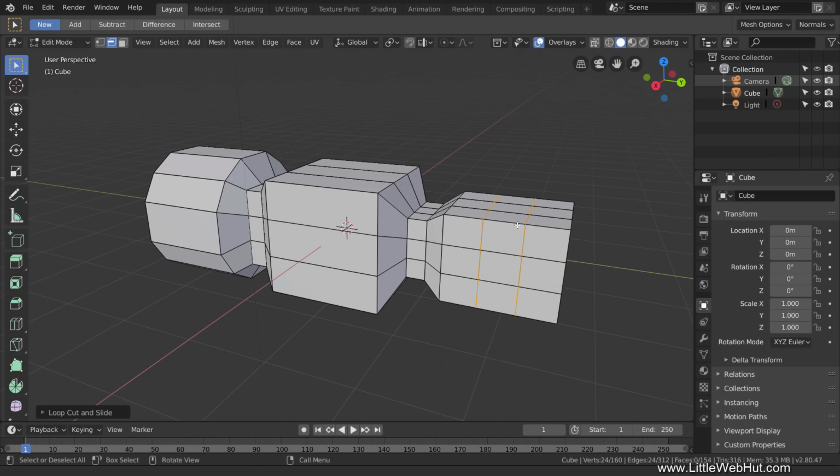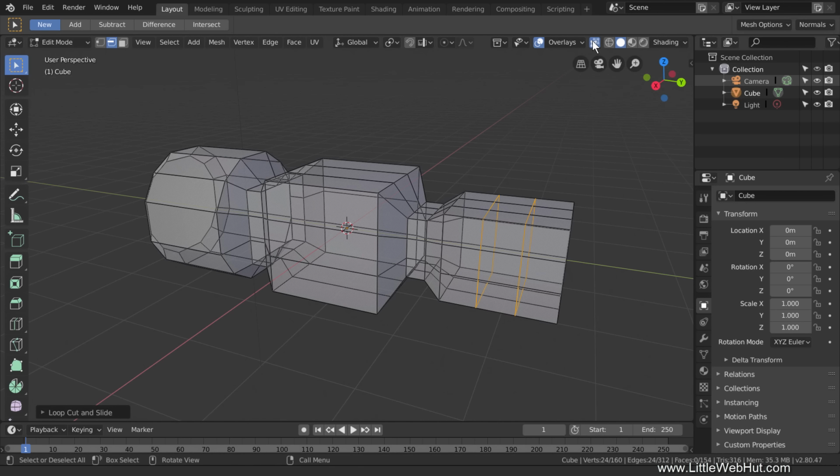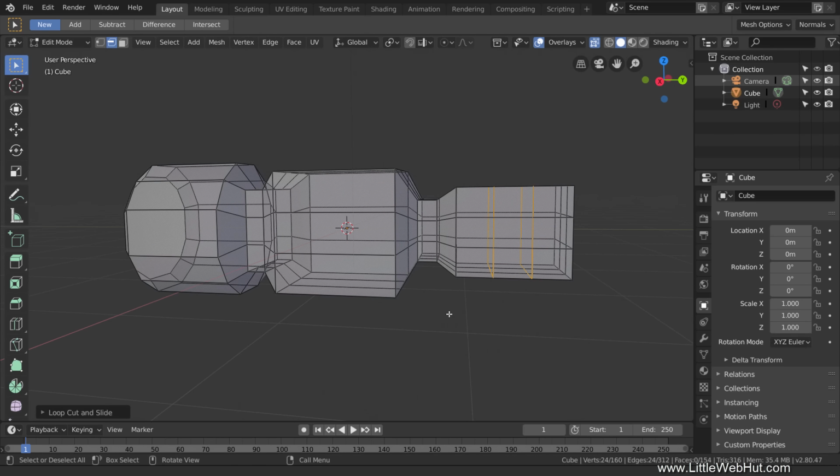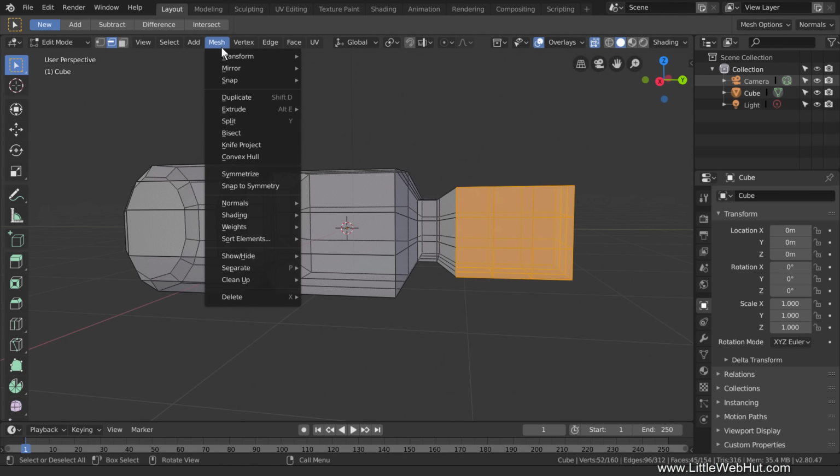Now we're going to transform this cube section into a sphere shape. So that we can select edges on the front and back of the object at the same time, click the Show Whole Screen Transparent button. This lets you see through the object, and it also lets you select any vertices, edges, or faces that can be seen. Now rotate the object to the side and select the cube shape. To transform this into a sphere, from the Mesh menu select Transform, then To Sphere.